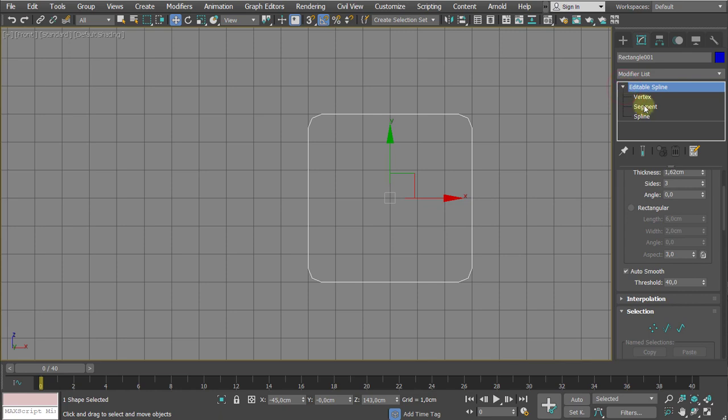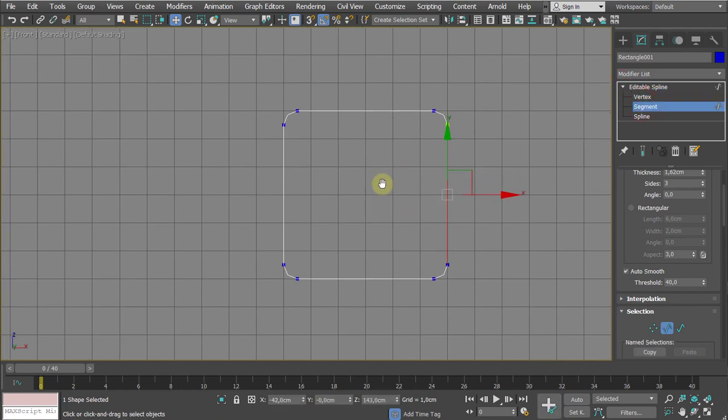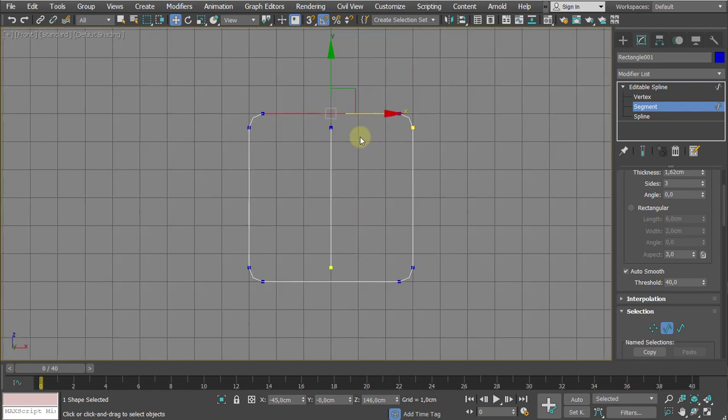The reason we're doing that is because we can select segments. We can actually copy segments, holding down the shift key, copy and drag. And if you want to make sure that this newly created segment is dead center to the original, we can use the align button, quick align, and clicking on the model itself will put this segment into the center.